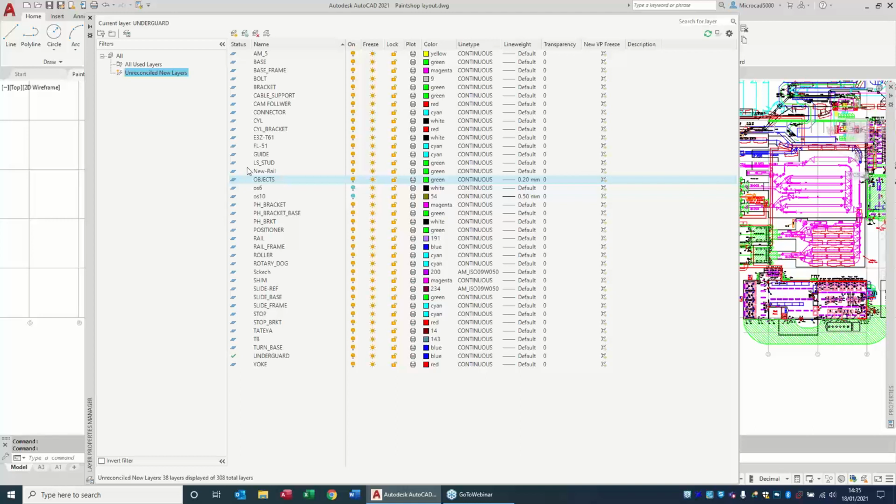Now, most of the time, the layers are set up in your drawing template file. I mean, it does help if, for example, you have some layer standard set up and there's a spelling mistake, or people are creating layers for text, annotation, notes, and it goes on. So it stops people randomly making layers.